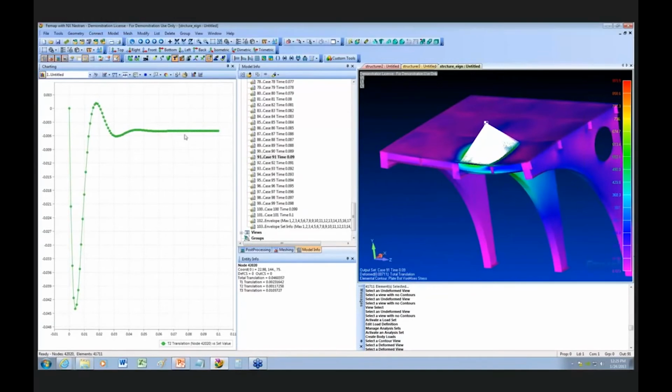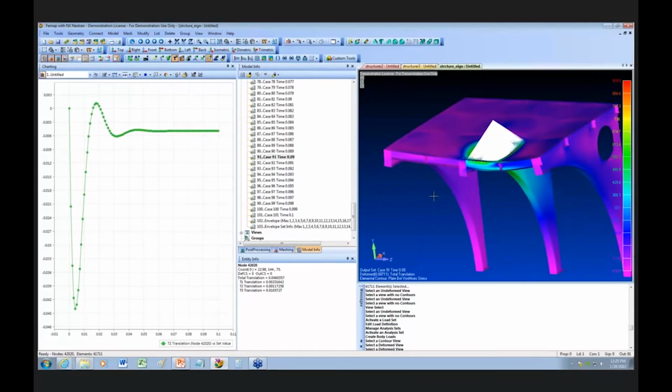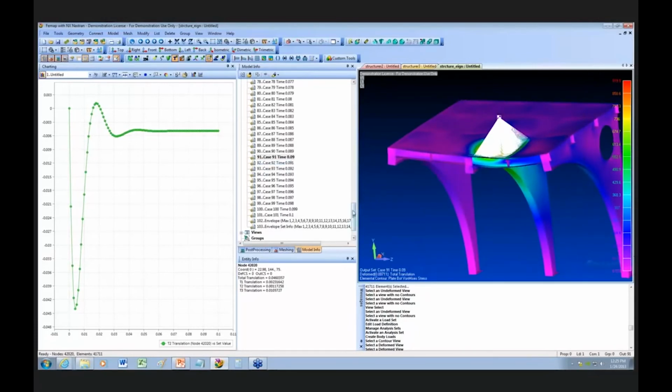Here's a point. I'm way down in this area where all the energy from that velocity has been damped out by damping. And now we're at a static solution, and it's almost like 920. So it's probably 15 psi off, very close. So actually, that's not a bad solution. But what we can see here is the contribution from the drop was a large contribution, but in a very local area.